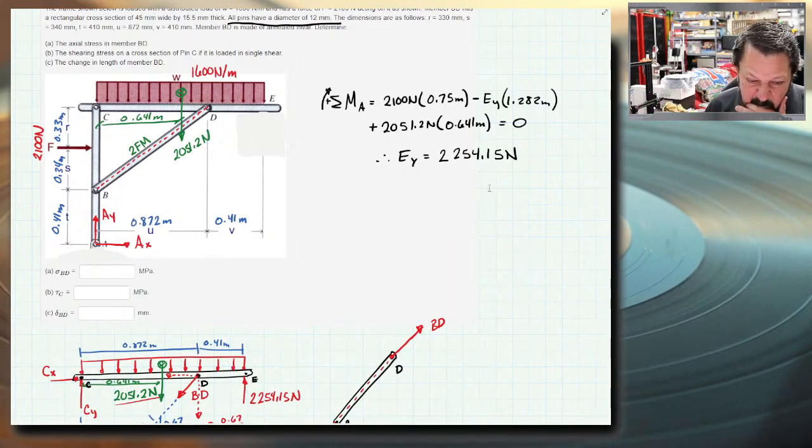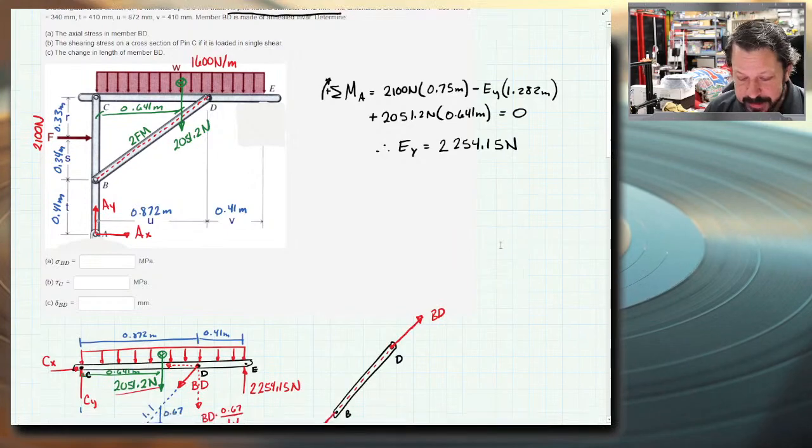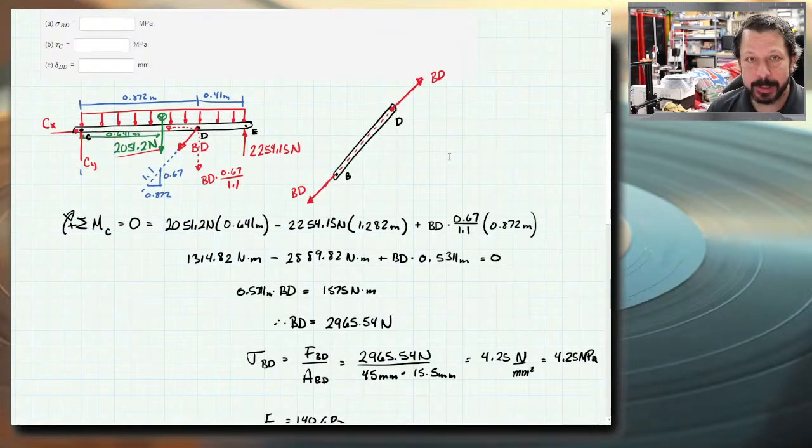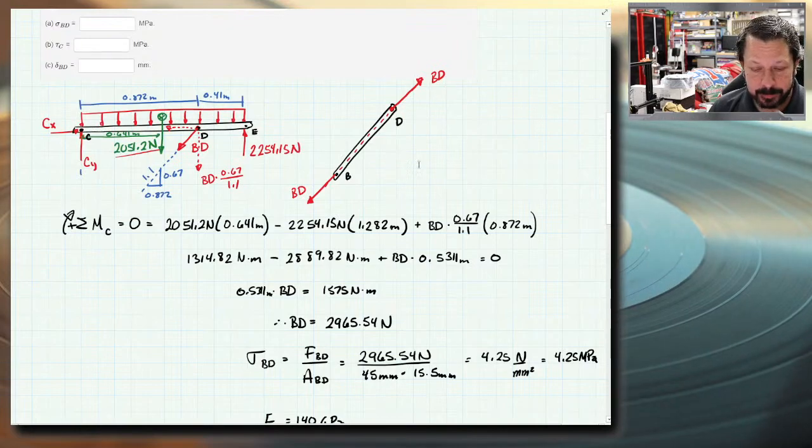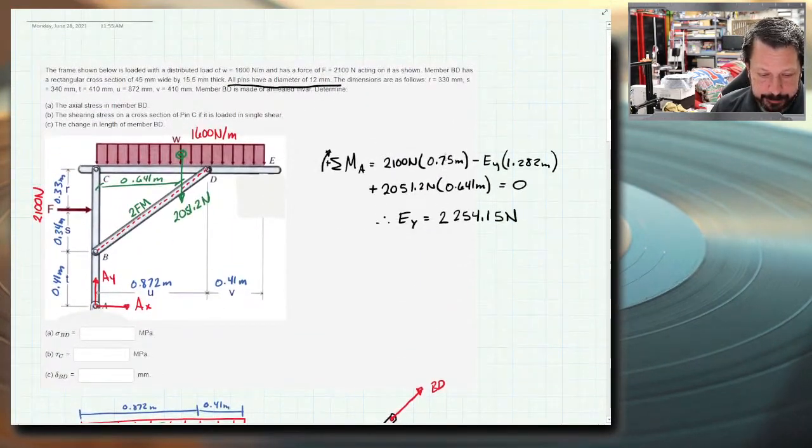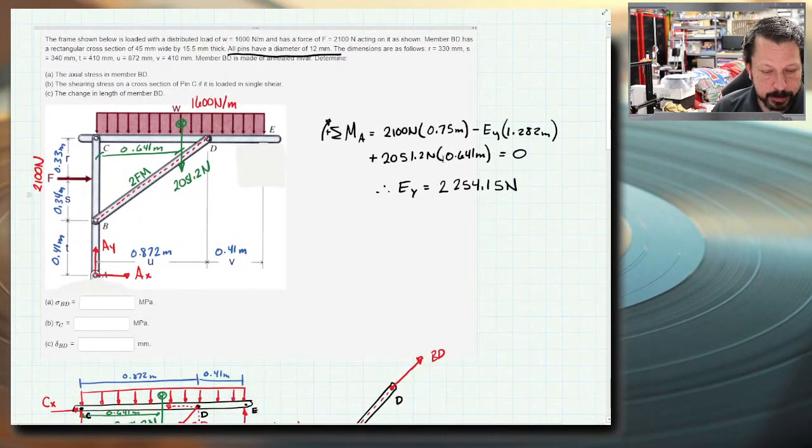So when you find the two-force member, you eliminate a bunch of your unknown values because you don't have to write dx and dy and bx and by. You just write the force in BD at both of those places. In fact, you wouldn't even need to draw member ABC. So that's a key part to it. But it's still one of the simpler frames and machines.